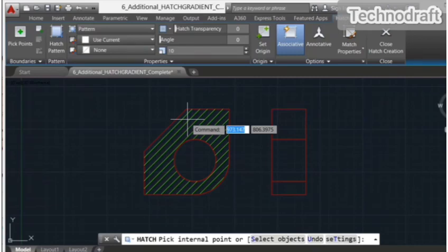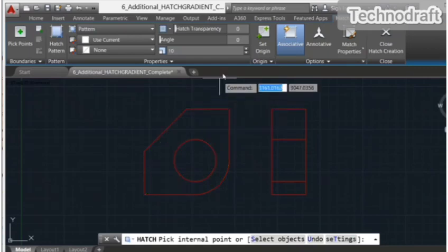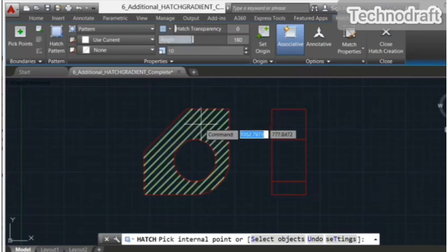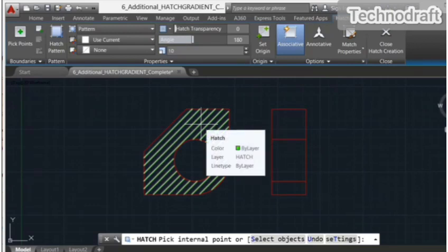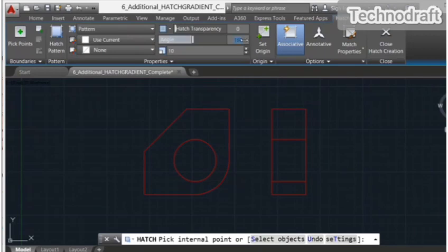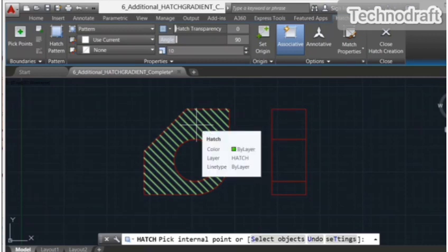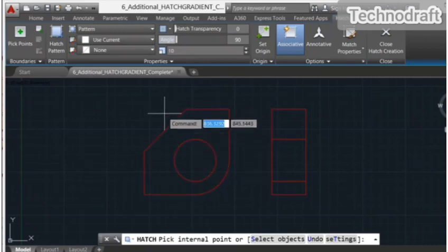Perfect. And I might want to change the angle of the hatch because it's following the lines at the moment. So I can come up here, type the value, and I want it to go to 180 degrees and press enter. If I hover now, it's going the same way, because I had twisted it around 180. If I change that back to 90, because I am already at 45 degrees, remember, then it goes the other way, which is how I want to go.